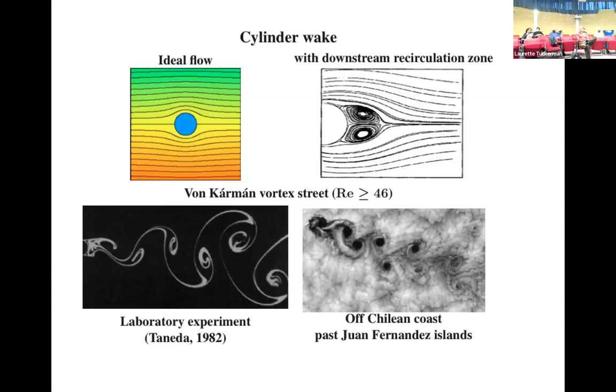Anybody want to know about that? Taylor-Proudman? Yes. In a sufficiently rapid rotation, the flow is the same at each plane. Can people see my hands or not really? It doesn't depend on the vertical coordinate.